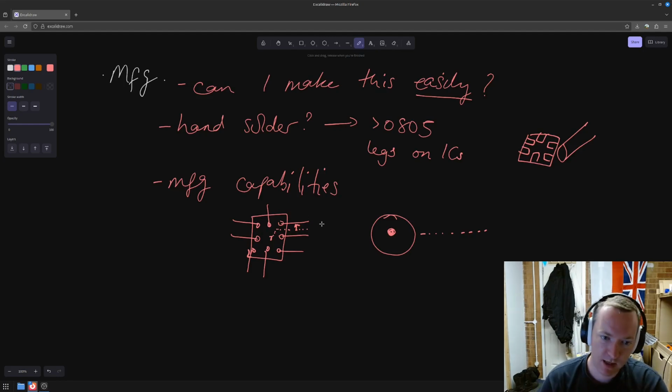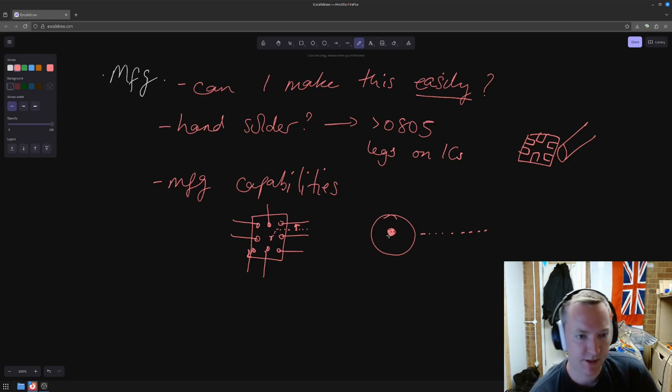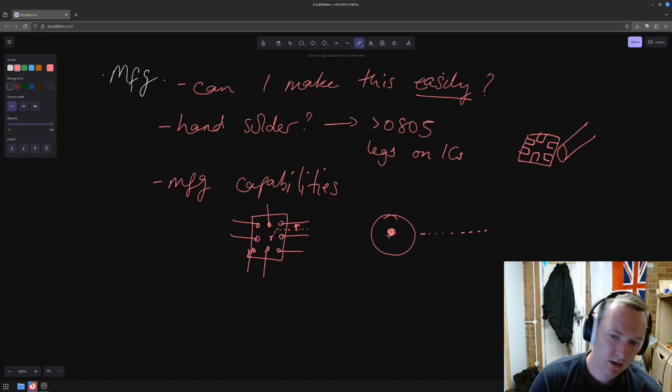So you have to go on an internal layer, and if there's no space for a via around it, you need a via in pad, and that's potentially another layer of cost. So, long way of saying, also consider what the manufacturers can do. A manufacturer can almost certainly do what you want. It's a matter of how much you're willing to pay for that.